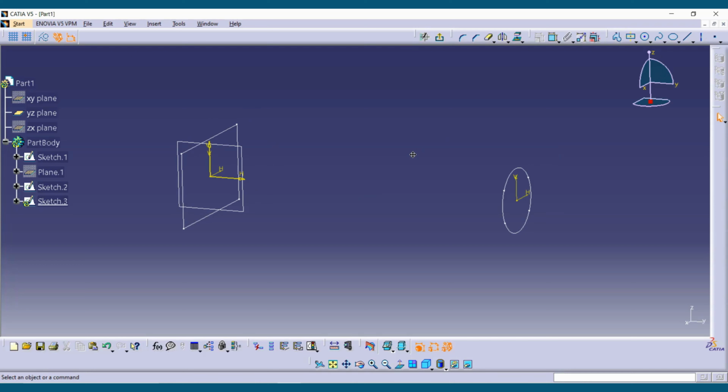So guide curve can be taken by any option. We can use splines, we can use lines, we can use arcs. Any option can be taken here. So I'm going to select spline only. Say first point, second, third, and this fourth point.